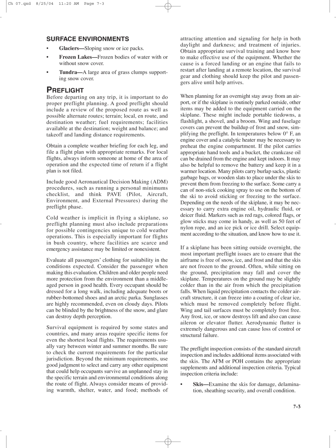Pre-flight: before departing on any trip, it is important to do proper pre-flight planning. A good pre-flight should include a review of the proposed route as well as possible alternate routes, terrain, local, en route, and destination weather, fuel requirements, facilities available at the destination, weight and balance, and takeoff and landing distance requirements. Obtain a complete weather briefing for each leg, and file a flight plan with appropriate remarks.